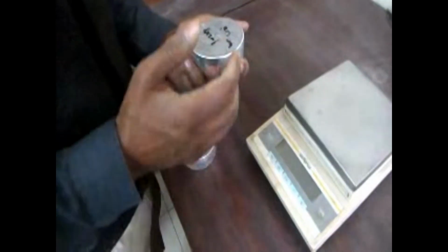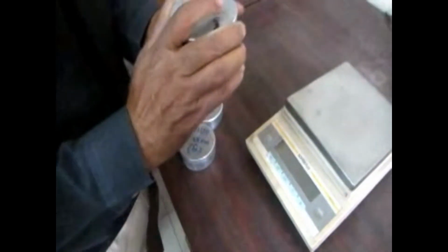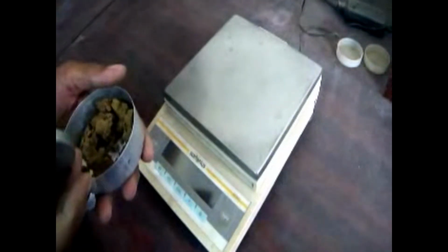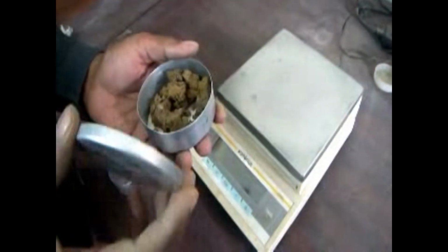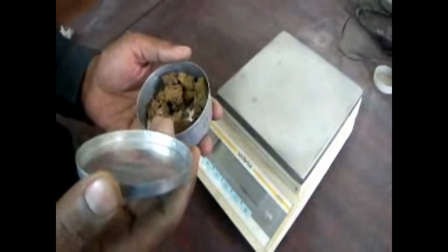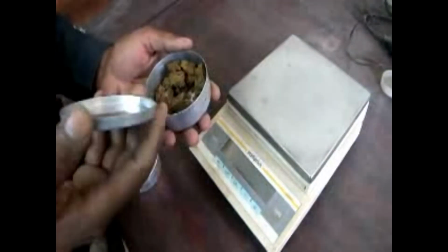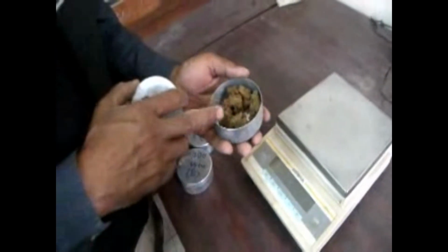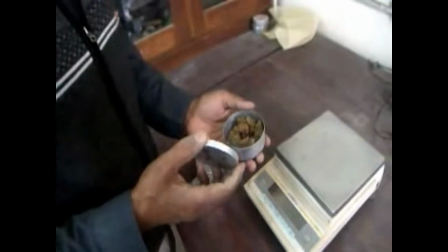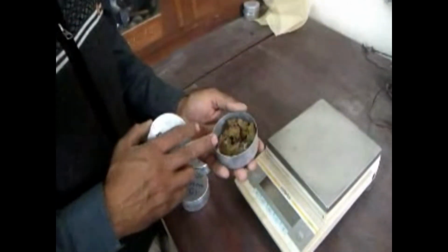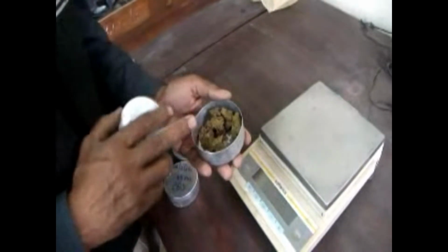And after 24 hours we will measure what is the weight of sample plus dried soil. Then we will remove the sample and find out what is the weight of empty box to find out what is exactly the soil moisture that was absorbed in this amount of soil, to find out finally the volumetric content of water in this soil.